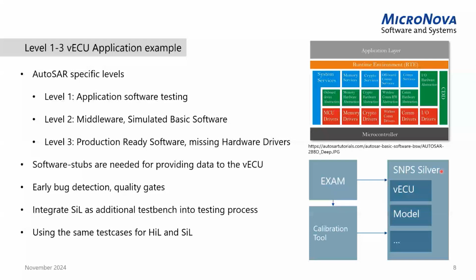And one typical advantage that we want to achieve here is that we want to use the same test cases for hardware-in-the-loop simulation and software-in-the-loop simulation, so that we get an advantage there by not having to implement the same test case over and over again.